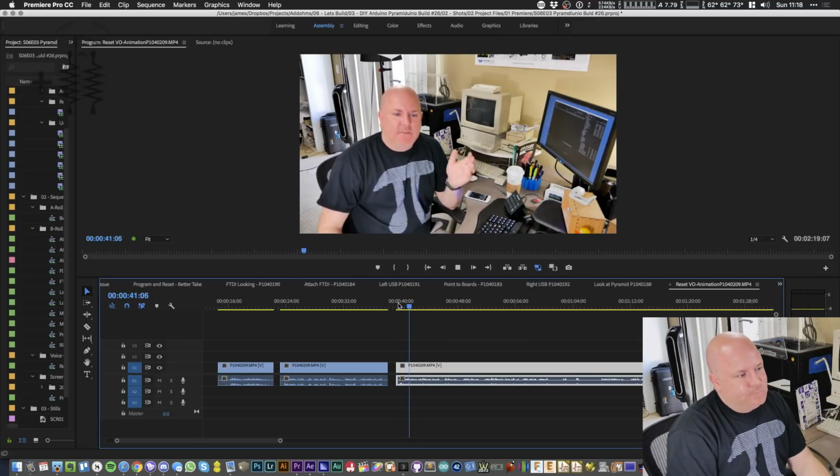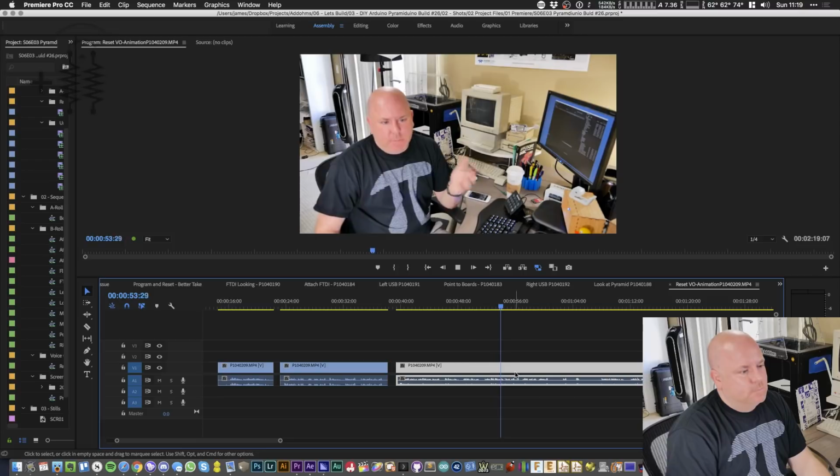Over on the 328 side, there is a reset signal, which holds the processor in a stopped or reset state. It has a pull-up resistor to 5 volts. The reset signal is also active low, which means when 0 volts or logic low is applied, the processor resets itself. It stays in that reset state until this signal goes high.